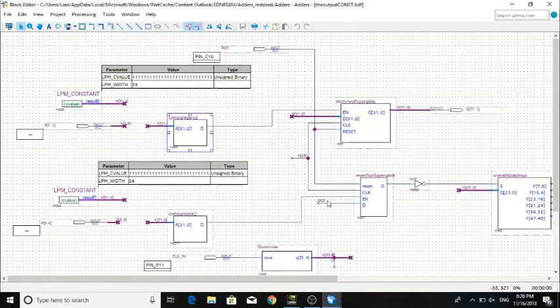If the last bit of data is 1, the NOT gate will turn this to 0, and this switches the 7-segment display off as it disables the 7-segment display. If the last bit of data is 0, the NOT gate turns this into 1, and the 7-segment display shows the value of the data stored in the register above. The output of the 7-segment display will be all 1s, but our 7-segment display is a common anode display, so no segments will light up.